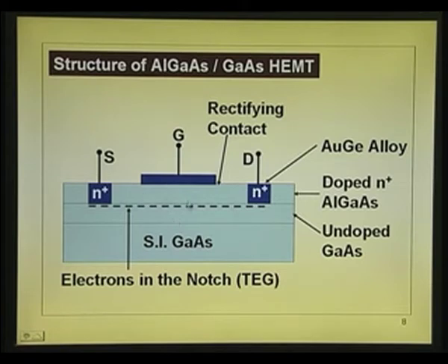So, you get a benefit of that high K, plus your benefit of the metal semiconductor contacts which produce a depletion layer. So, current flows only through that, plus you can apply voltage between this and this, and control the charge here. Just like in the case of MOSFET.